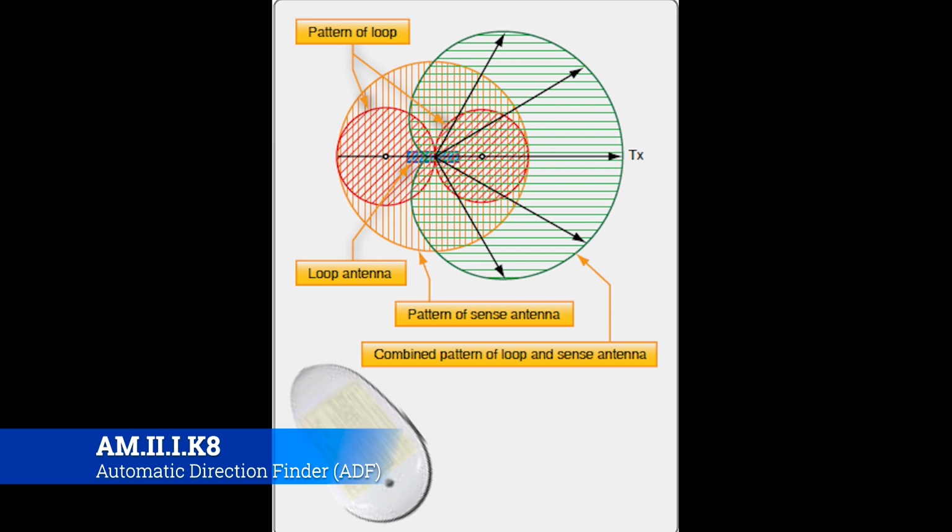It's just like any kind of triangle. It knows the distance between the front antenna and the rear antenna, and once it has those two points, that's one leg of the triangle. Then all of a sudden, if we can make a guesstimate that this signal entered the pattern of the loop field at this angle and at this strength, well, the strength will give us the length of a leg of the triangle, and then the direction it hit from will give us an angle to shoot from, and that should also correspond with the pattern of sense antenna.